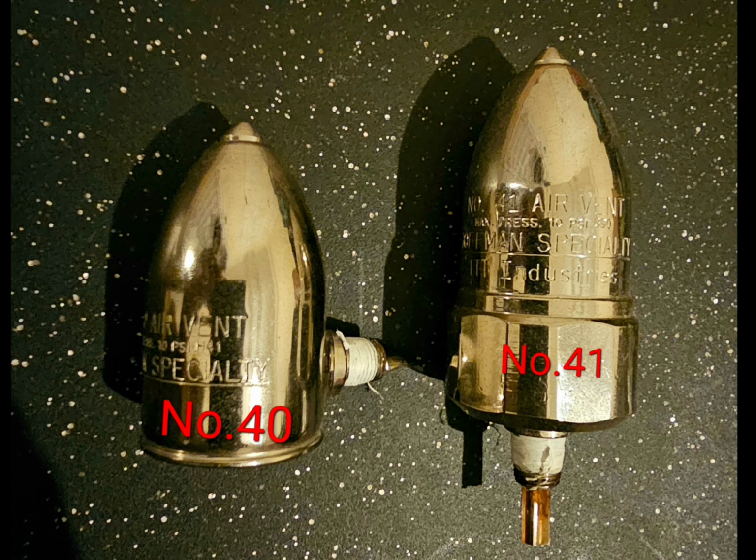And what you're going to have is fluctuating temperatures. Instead of your radiator being able to heat your room at the same rate that the heat timer or the thermostat has it calling for heat, you're going to notice it's not going to heat up the same way. Because why? You have this constant fluctuating temperature, up and down, up and down with the radiator. Why? Because the vent itself is not the proper vent for it. This is why you want to stick with an air vent that has either a 1/8 inch opening or 3/8. That would be best for convectors.